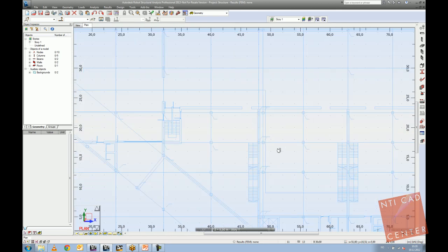That might be dangerous because in many cases, again, in AutoCAD, you have this sort of a floating comma. So you might have 10 numbers after the comma. I think Robot is capable to import, I don't remember that exactly, but I think it was something like 8 numbers after the comma when you import from AutoCAD. So it might get really imprecise data, let's say, and Robot doesn't do roundup itself.